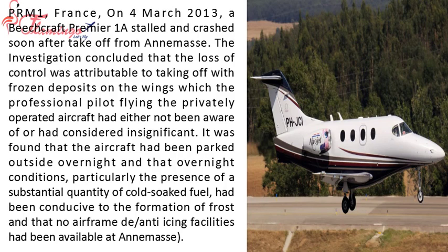It was found that the aircraft had been parked outside overnight and that overnight conditions, particularly the presence of a substantial quantity of cold-soaked fuel, had been conducive to the formation of frost and that no airframe anti-icing facilities had been available at Annemasse.